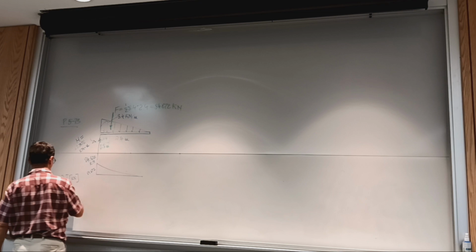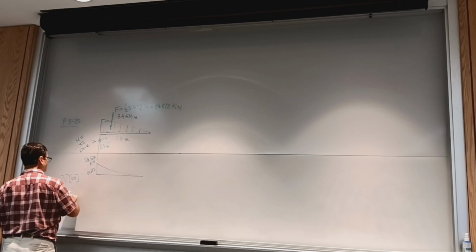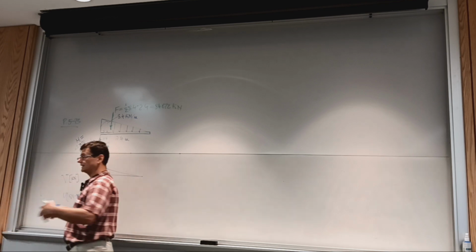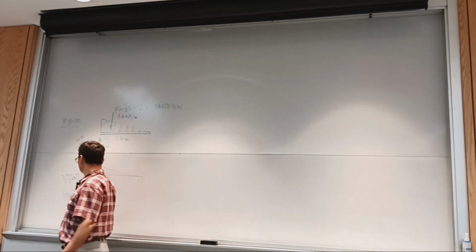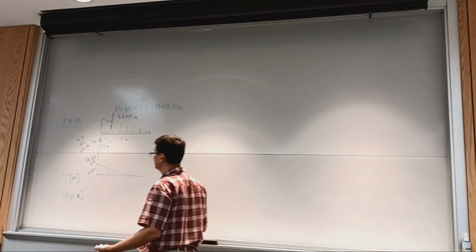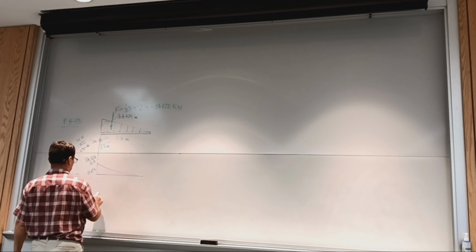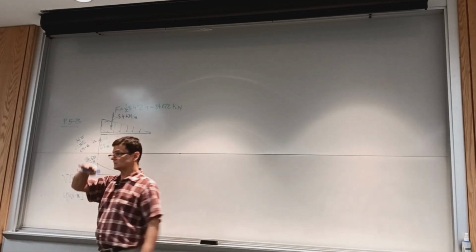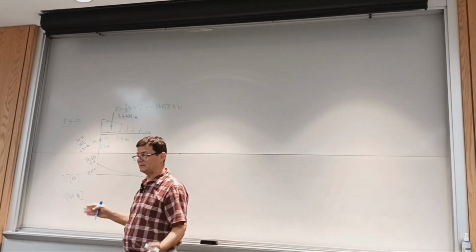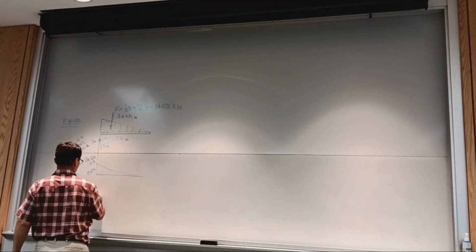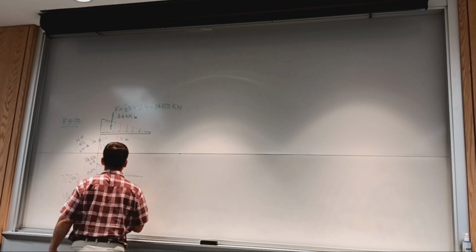All right, and the moment diagram M is going to be in kilonewton meters. Once you do a stress calculation, of course, you switch to more convenient units, say newton millimeters. Anyway, on the moment diagram, the beam is going to be hogging, so the entire moment diagram is going to be below the x-axis and begins with a drop.